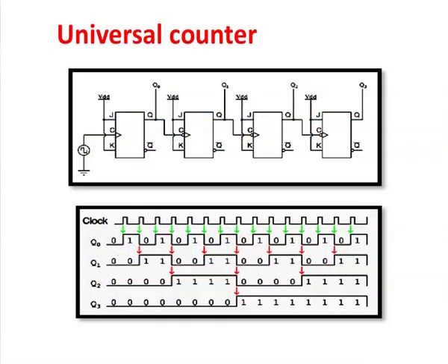Here, the heart of this frequency meter is the decade counter. As we know, basically it is a digital counter which comprises a number of flip flops, basically JK flip flops, which are connected such that the output of each JK flip flop acts as the clock input to the next JK flip flop, and obviously all the JK flip flops are in toggle mode.